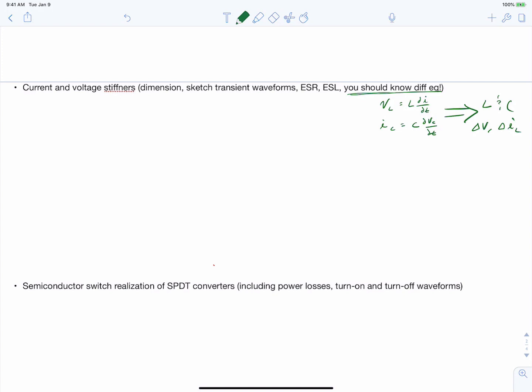We've also talked about the equivalent circuit of these devices, how when you think you're buying a simple capacitor, you're actually getting an equivalent circuit that has a resistance and an inductance and a capacitor. And we've quantified these, we've labeled these as an ESR, and ESL, and our desired capacitor. We've talked about how to read data sheets to determine these values, and how to read data sheets to see how components derate based on temperature and based on frequency.